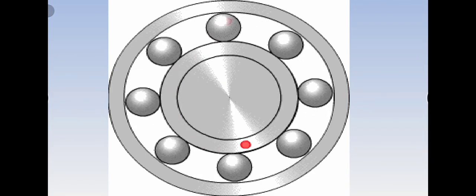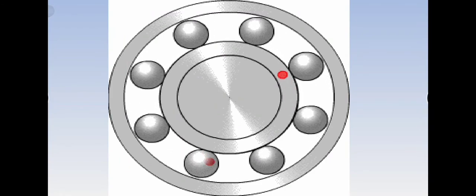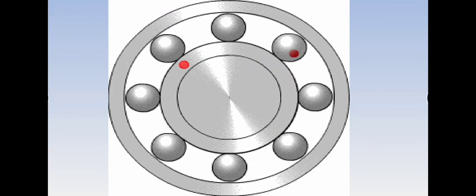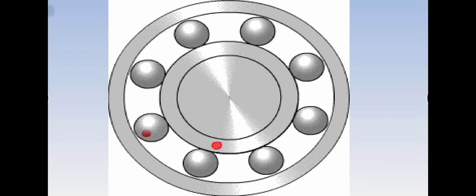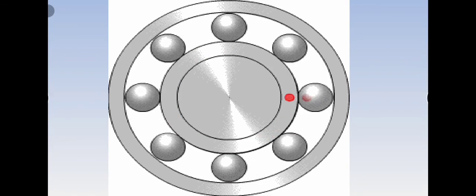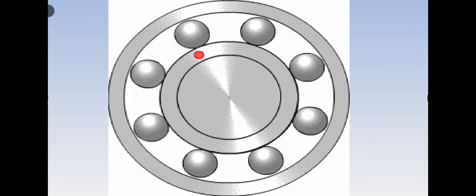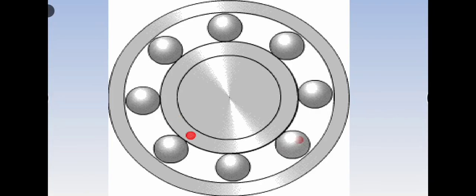Advantages of using ball bearings. Ball bearings have good wear resistance. They do not need much lubrication. They provide very low friction. They have a long service life and are easy to replace. They are very cheap to buy and can handle thrust loads. Disadvantages of ball bearings: they may break due to shocks, can be quite loud, and cannot handle large weight.